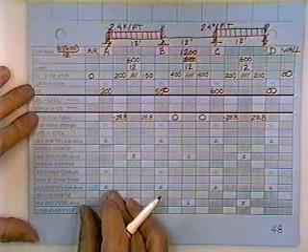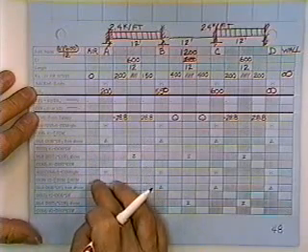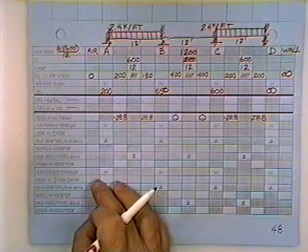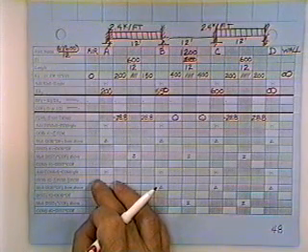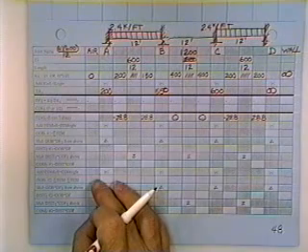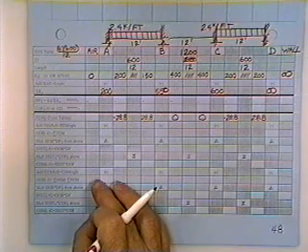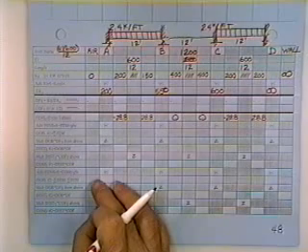Now the sets of numbers inside the black lines are numbers that you use in computation from then on down the table. The distribution factor is discussed on page 44. It tells you how to compute them. Basically, it answers the question, if a guy standing at joint A is holding on with a moment of 28.8 registering in his torque wrench, and he lets joint A go, where would the moment go?